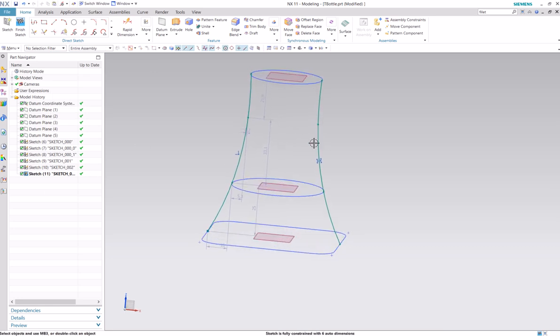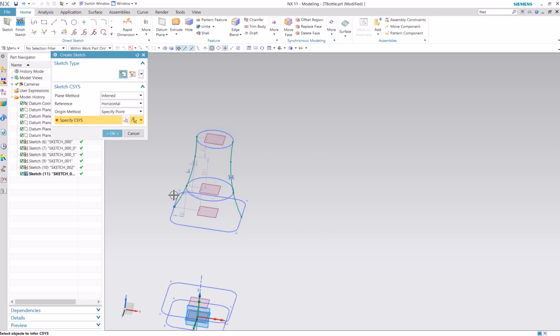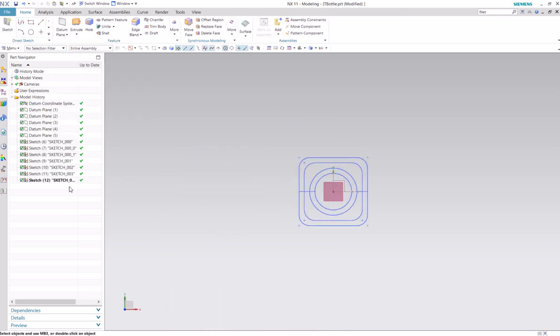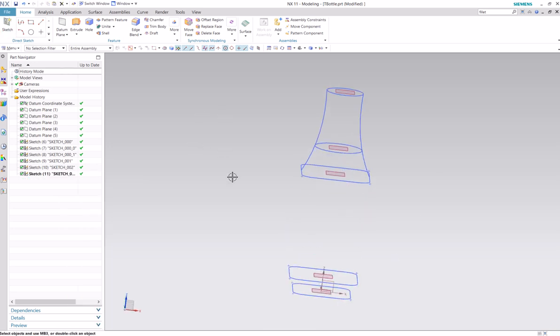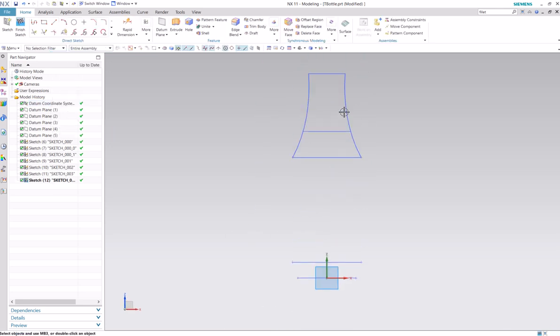Okay, that's just going to be a guide. Maybe we can select it later, but at least for using guides with a sweep kind of a thing, you can't have two at the same time, so we'll just draw it in separately here. So yeah, same plane. Oops, not that one. Okay, this guy here, thought it had that one selected before, that looks fine.